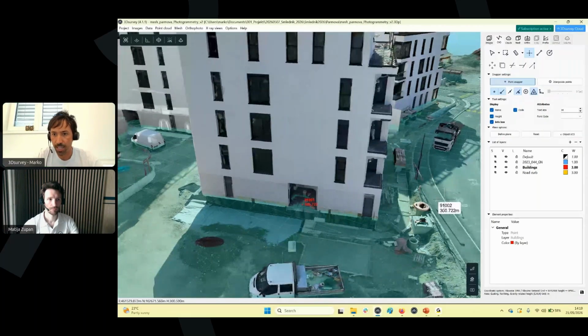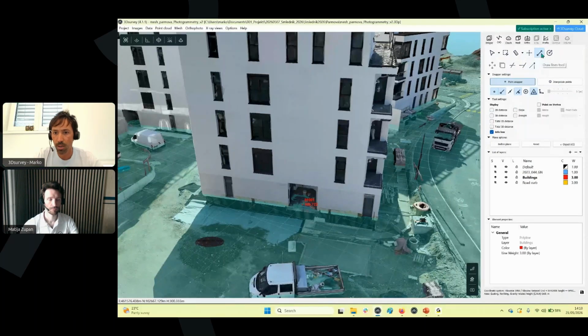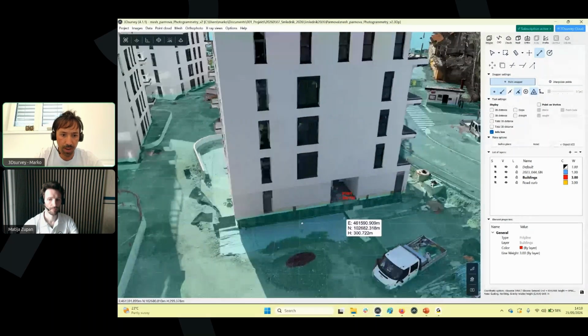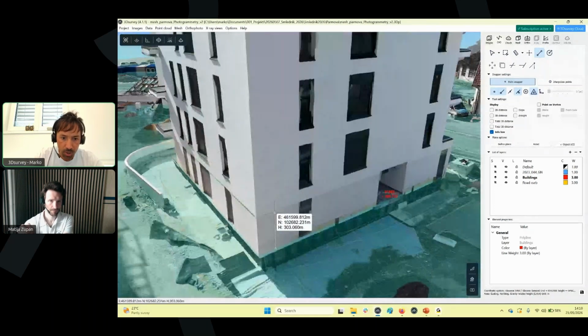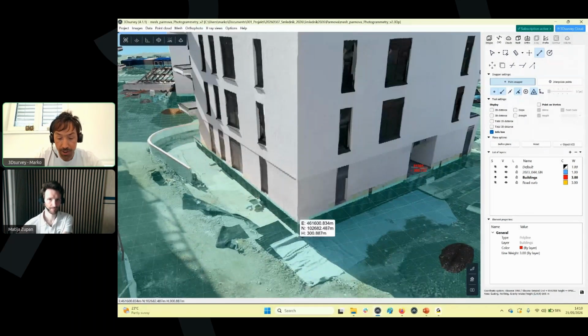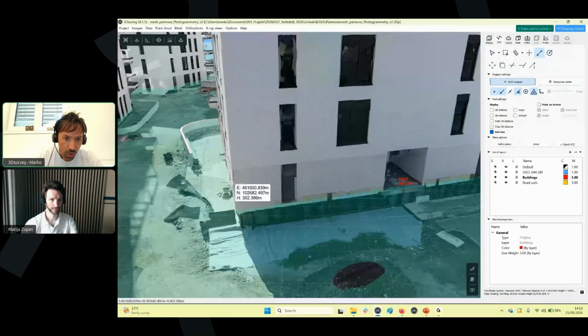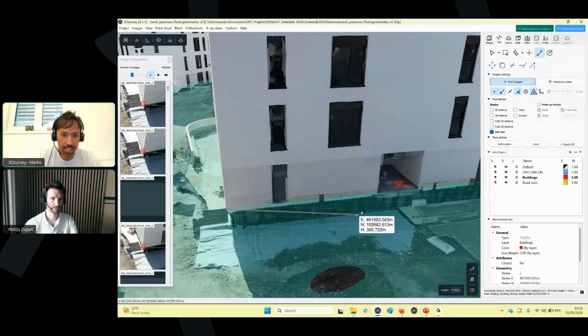Okay, I have the right layer. I will go and take my draw line tool. I don't need point on the vertex. If I would like to have it, I could have it maybe later on. And I can start with my first corner. So I don't need to snap now and figure out where is this exact height, because even if I go up here, you will see we are snapping down to the plane. Watch now, left mouse click, immediately I start connecting. You see where the line is attaching.